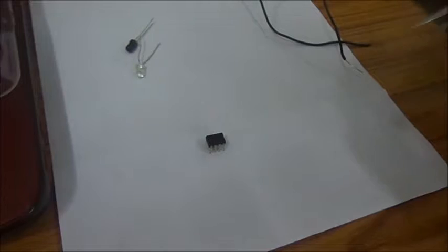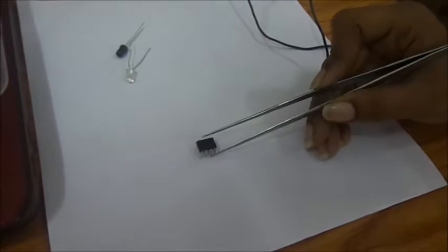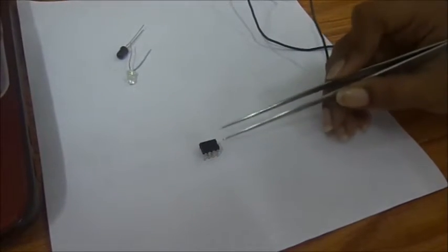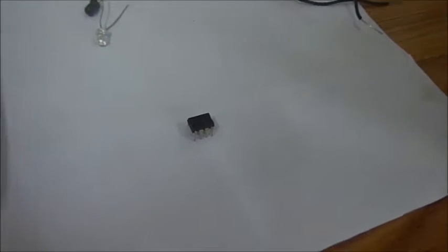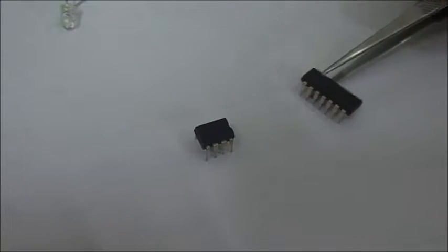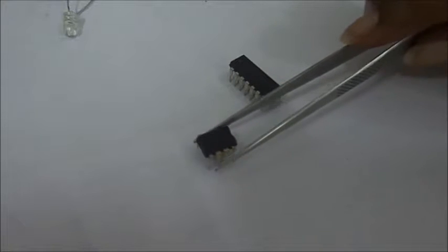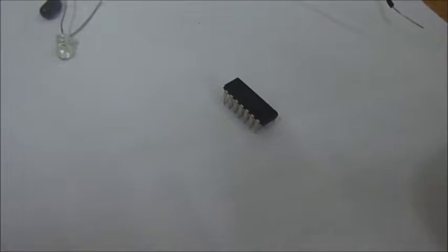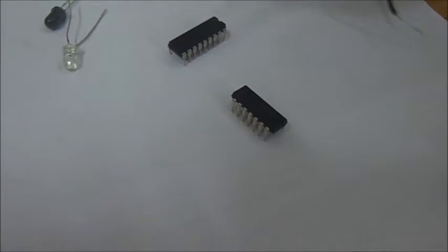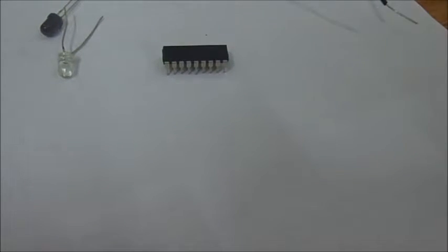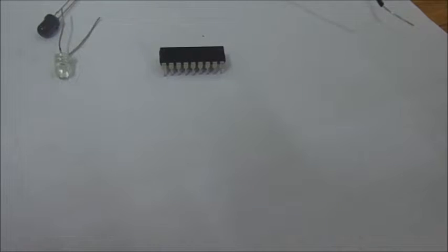The amplifier section amplifies the input from the two input chambers. We are using the INA126P instrumentation amplifier for amplification purpose. After the detection of input, the microcontroller converts the analog input to digital samples and also transmits them to a transceiver. Another important function of the microcontroller is to drive a buzzer and an LED when the input is detected. To drive the buzzer, we are using a ULN2803AN IC and LM324.